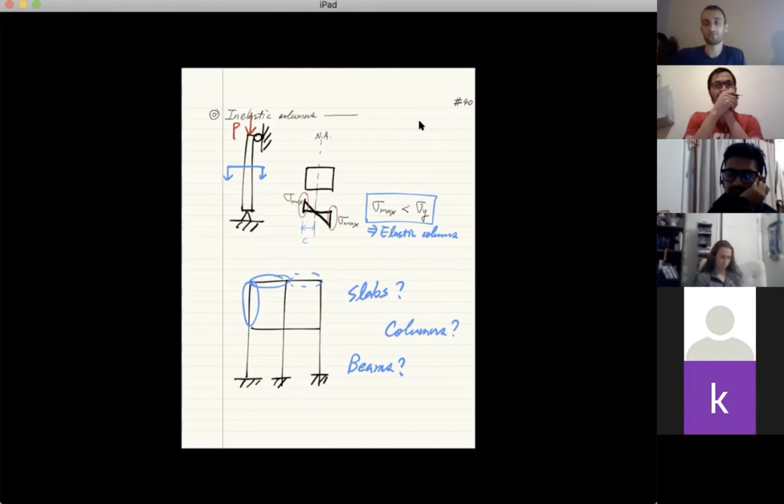Now, the easy way to explain this is to look at what we call load transmission paths. That means when the structure is designed for taking loads, what is the transmission path for this loading? Suppose you provide this total force, defined as W times the entire cross-sectional area, and then you pass it to what? The loading is carried by slabs, and the slab will pass the loading to what?